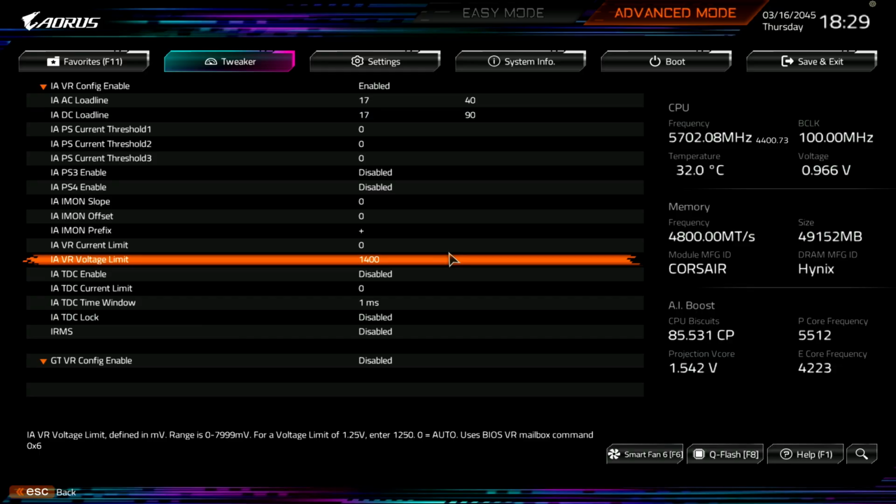So the voltage jumps up above the target voltage, which, if your target voltage is basically the same as the VR voltage limit, then yeah, that overshoot is going to go above that VR voltage limit, right? Like, if we send a VID request for 1.4 volts, we have 0 V droop or close to 0 V droop with Extreme LLC. So we're going to be sitting at, like, I don't know, 1.38 volts or something. And then we get overshoot that'll go like 50 millivolts. We'll end up at like 1.43 peak.